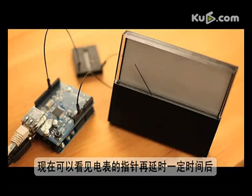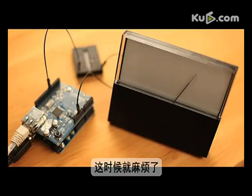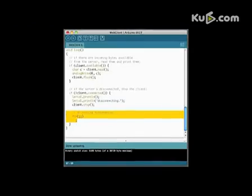If we were able to make a successful connection to get our byte, our panel meter should be at the 75% mark, since the value 191 is about 75% of 255. If you don't get 75% on your meter, I would troubleshoot by putting the server's output back to the serial monitor to see what's going on.